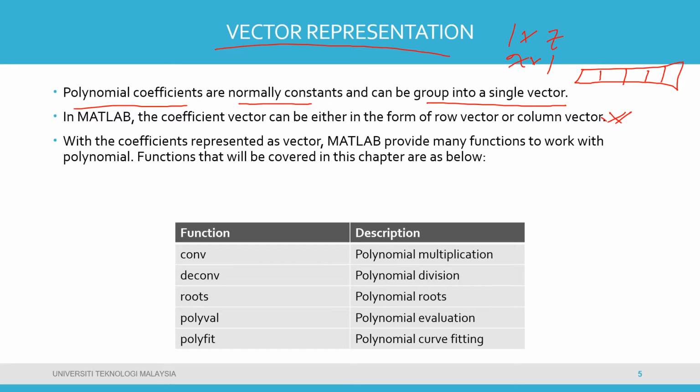With the coefficients of a polynomial represented as a vector, MATLAB provides many functions to work with polynomials. These are the MATLAB functions you can use. For multiplication you can use conv, and for division, deconv. You have two parameters.